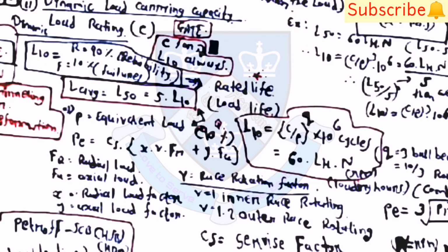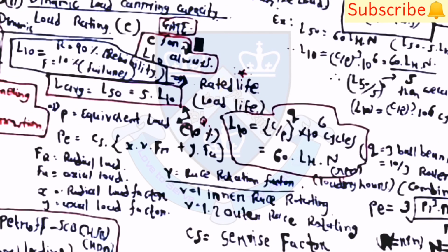Then there is one more important topic, dynamic load carrying capacity, or you can say the dynamic load rating. The equation for this term is L10 is equal to C by P raised to Q into 10 raised to 6 cycles, where Q is equal to 3 for ball bearing and Q is equal to 10 by 3 for roller bearing.